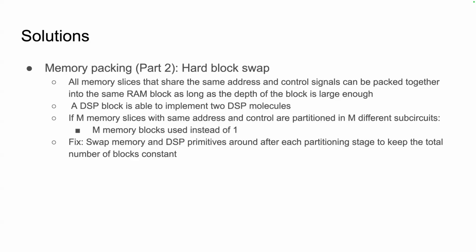okay, now let's say you're adding together 4 9x9 multipliers. You get 4 mac mults and then 1 mac out, adding them all together. So you wind up with two kinds of primitives going in, some of which have to be chained together if there's some complicated things. So I'm not sure why they say there's two types of primitives that go there. They're not always going to be two things. Sometimes it'll be a different number.